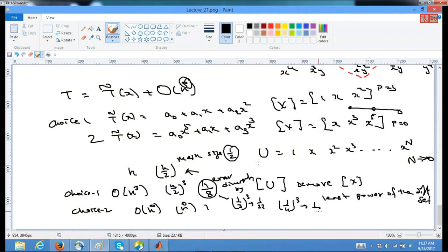Whereas in this case, for all the cases, the error would remain the same. You will think I did every formulation exactly the same, but your choice of basis is so bad that it results in no mesh convergence. By increasing the number of elements, you would never see the error diminishing because you left out the lower powers.